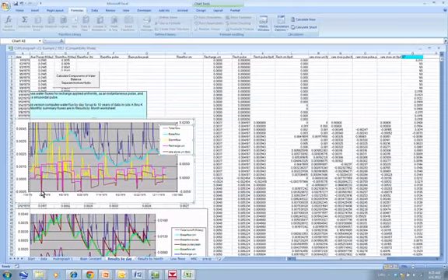Okay, so what we also have is the change in storage, and that's shown here by this brown line. You can see here where we've got some high recharge, the change in storage is positive. Again, we are using this scale. And then down here, we have a change in storage that's negative. In these places where the recharge is relatively small, or 0, the change in storage is negative, so water is being depleted from the aquifer. That's the interpretation that we get from this analysis. So we really get quite a good bit of insight into what's going on in this particular aquifer.